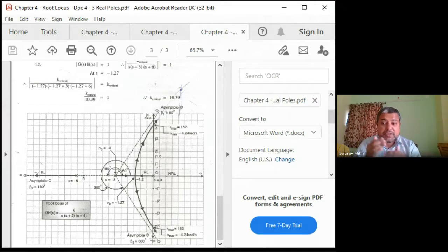That means as you are increasing the value of k, you are going to find that the poles are shifting towards the right. That means the real part of the pole position is actually reducing. And real part of pole reducing means the system is becoming more and more unstable because it is shifting towards the j omega axis. So this is actually the root locus of a three pole system, all the three pole system.